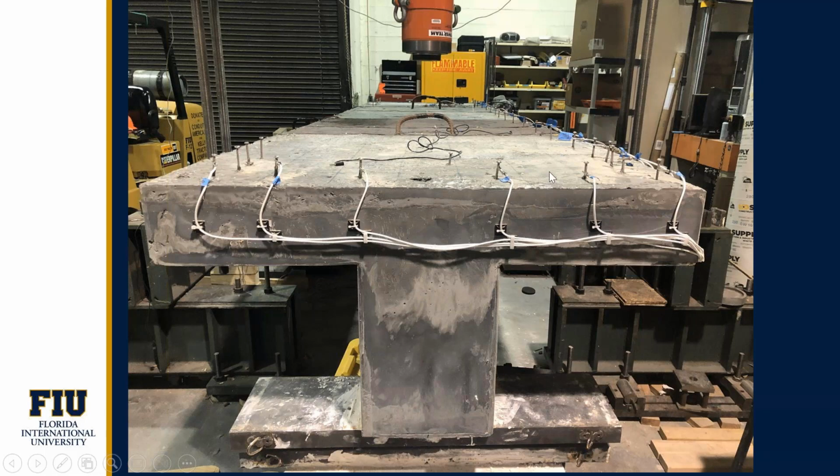Kingsley Law did lots of corrosion studies trying to see if we can get some information with respect to the durability, and everything pointed to the fact that wrapping this T-beam with the UHPC really chokes the system. It doesn't let the oxygen and the moisture be there at the same time, and it chokes the system. In fact, it reduces the corrosion rate. We let the specimen sit about 2 years in the lab.